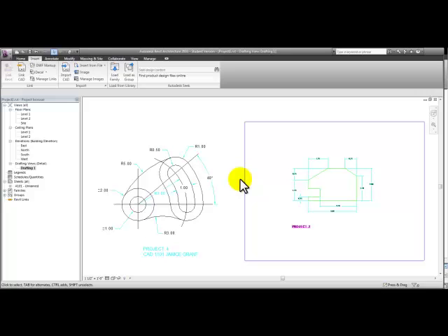It is suggested that when you import CAD details or even link the CAD files, you consider taking out the text, hatch, and dimensions, because when you bring them into Revit, they may not be consistent with the standards that you've established in Revit.